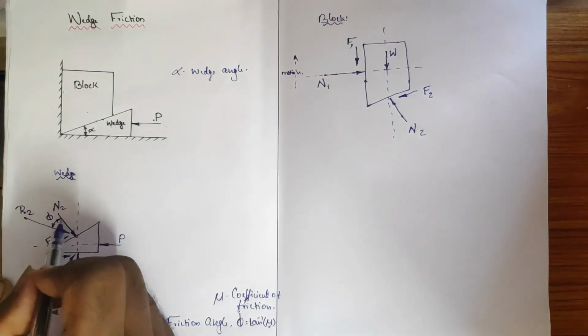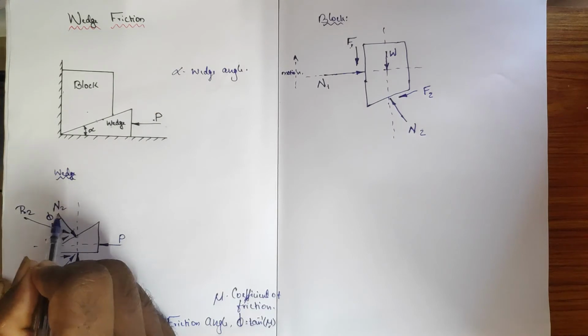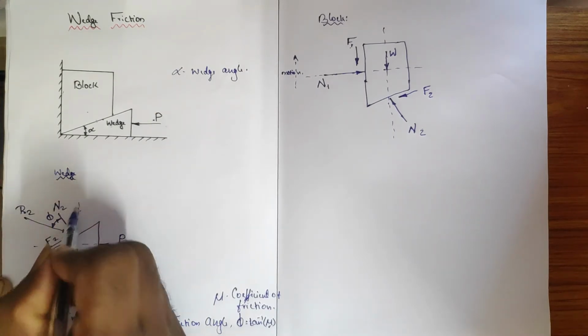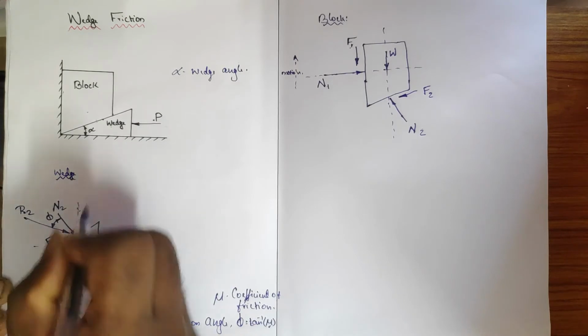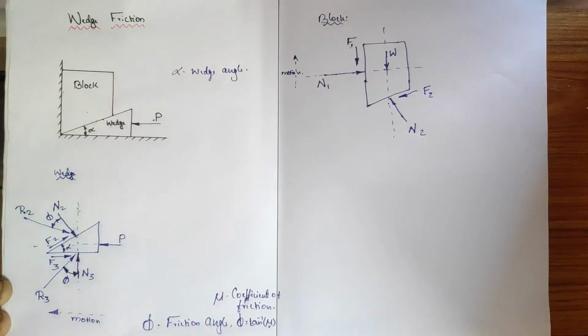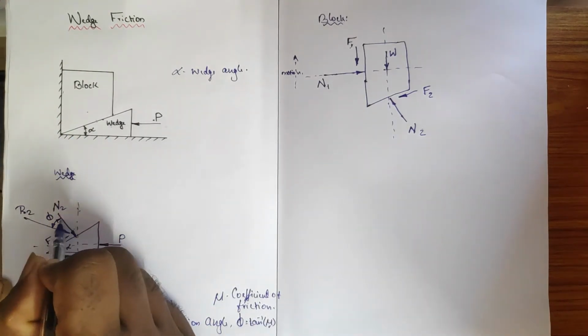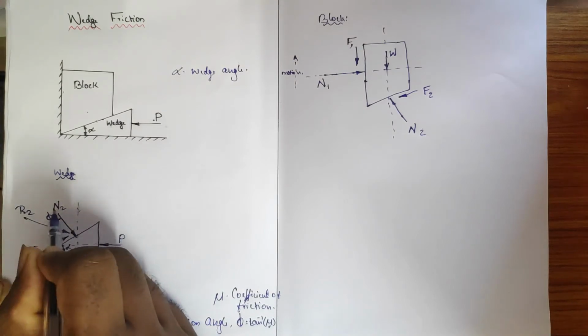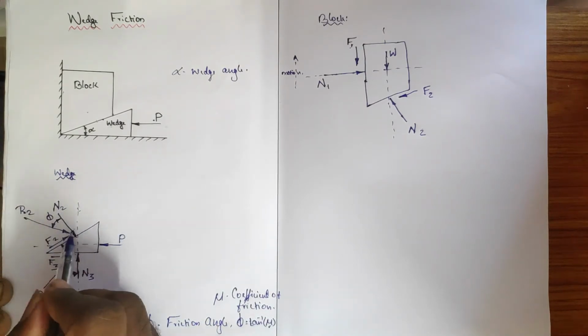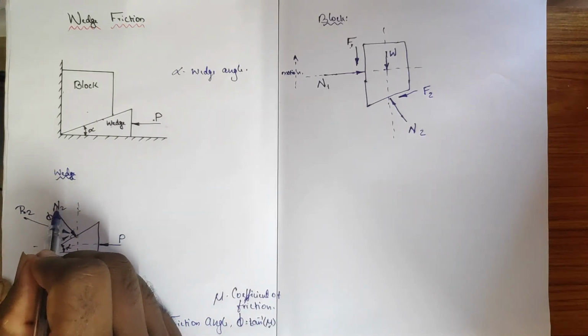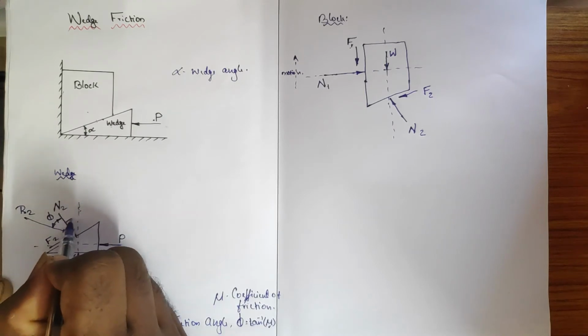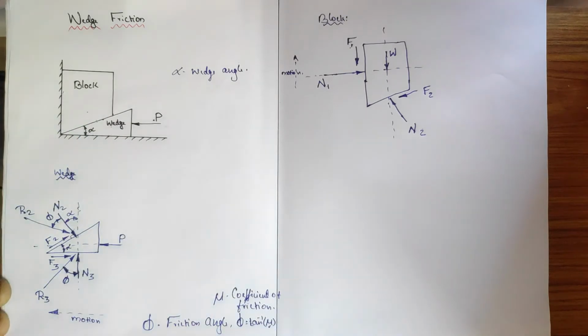And you may think, what would be the angle between the normal and this vertical component? Okay, it's so simple. The plane is inclined with alpha, right? With alpha, the wedge angle. Definitely the difference between this line, the force N, which is drawn 90 degrees to the plane, and this vertical component will show the wedge angle.